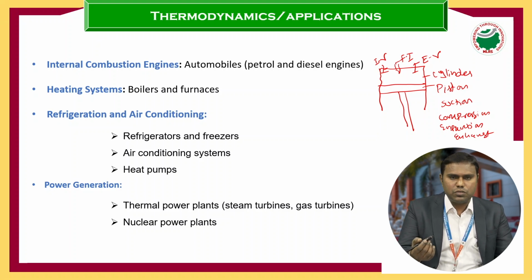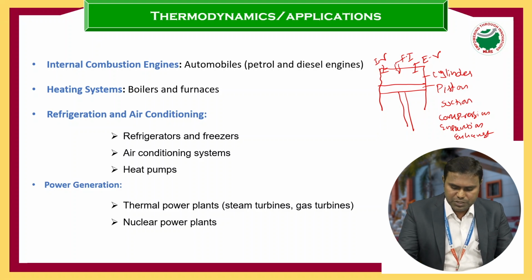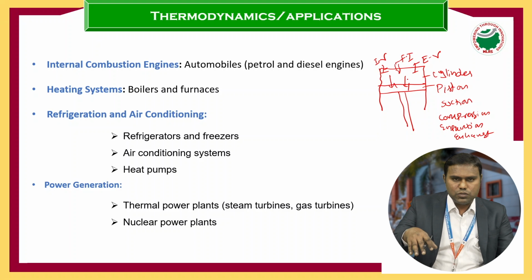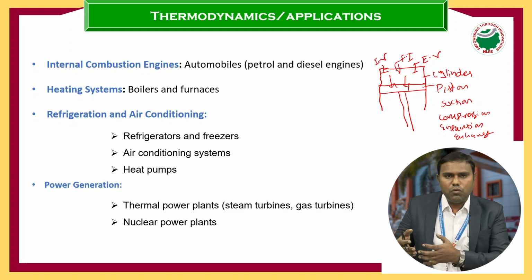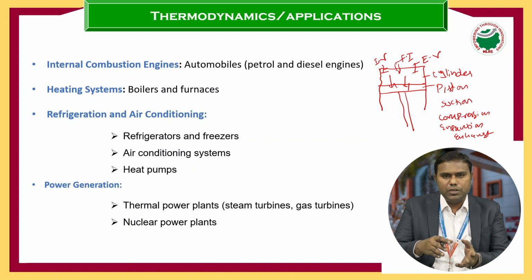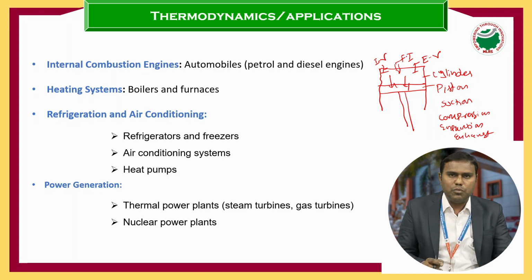At the end of the compression stroke, fuel is injected with the help of a fuel injector. Then due to compression ignition, fuel burns and produces heat energy, and because of this heat energy, the piston moves in the downward direction and produces work. So the concept is that we give heat input and get work output, the conversion of heat into work. Discussing this behavior is called thermodynamics.